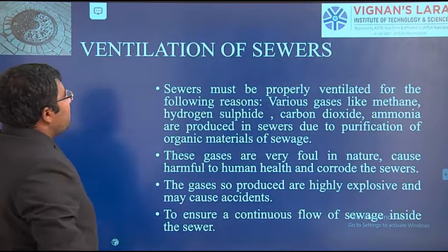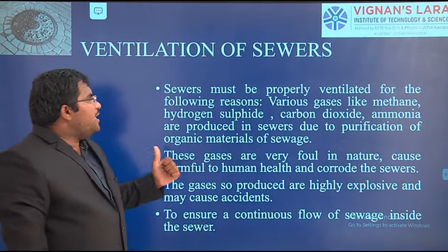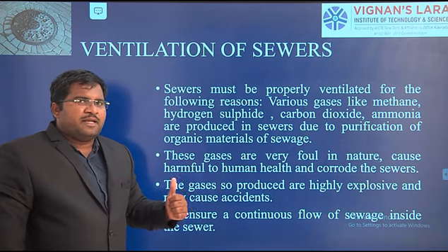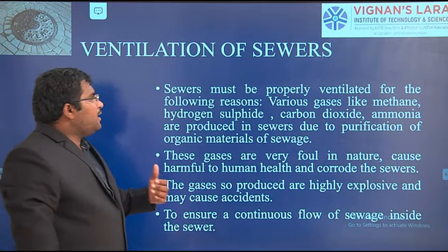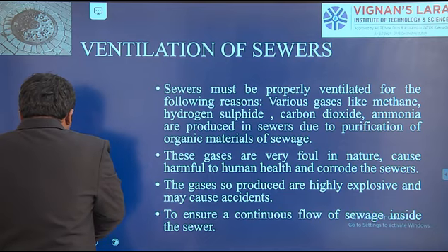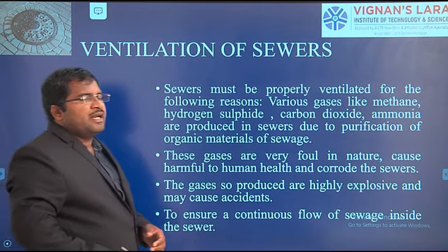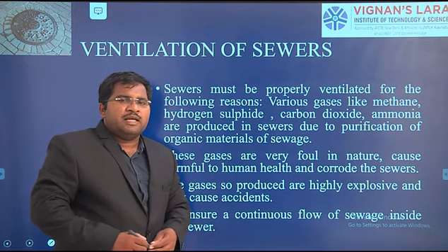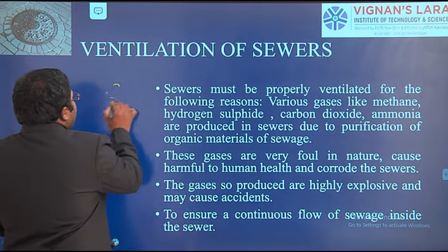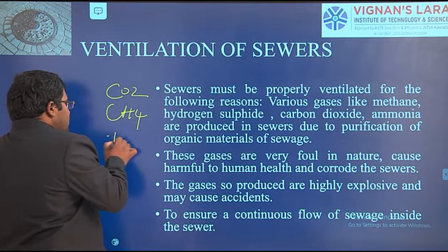Okay. Next, ventilation of sewers, right? I already explained ventilation of sewers earlier. So when is ventilation required? Whenever anaerobic reactions occur due to the organic matter in the sewer lines, there is a chance of generation of CO2, methane, and H2S.